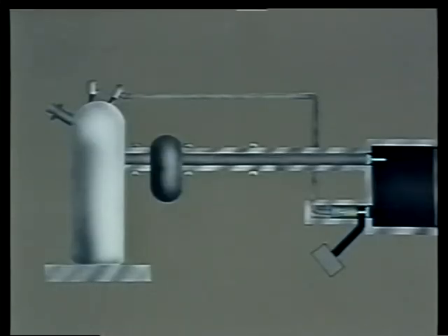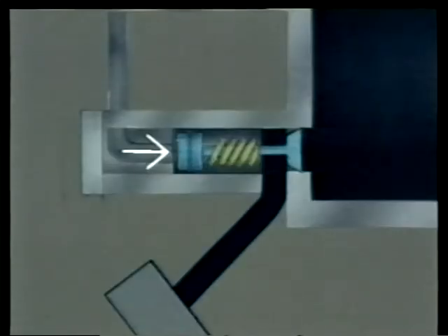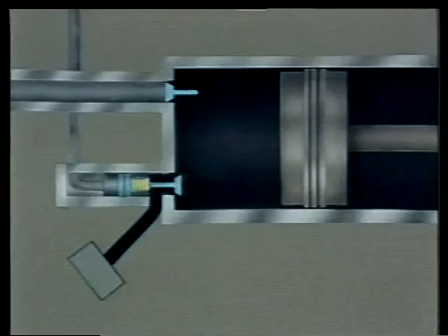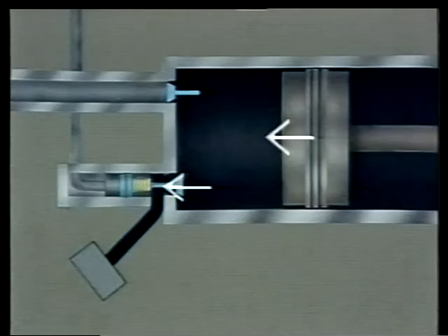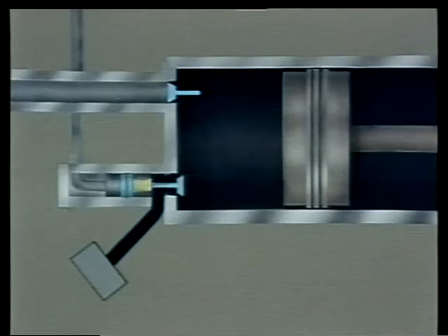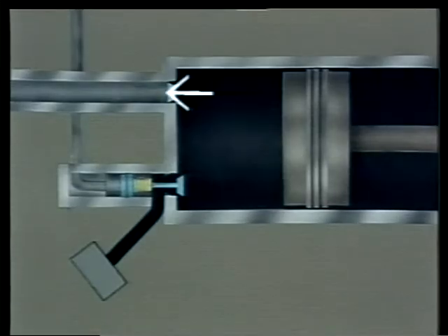The receiver has a pressure sensor. When it senses normal pressure, it opens a valve sending high-pressure air down a line to the inlet valve. The air pressure holds the valve open. On a downstroke, air enters the cylinder normally, but on the upstroke, air flows back out the inlet valve, so the piston isn't compressing the air. In this unloaded position, the motor and piston continue moving at their normal speed, but no compressed air enters the discharge piping.